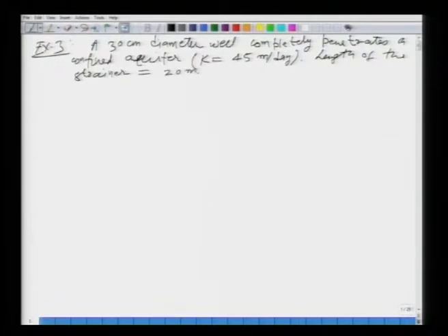What is a strainer? Well, strainer is a casing in the confined aquifer through which the water gets filtered, so that no sand or debris is coming in. So, basically what this length of strainer is representing is the thickness of the aquifer equal to B.